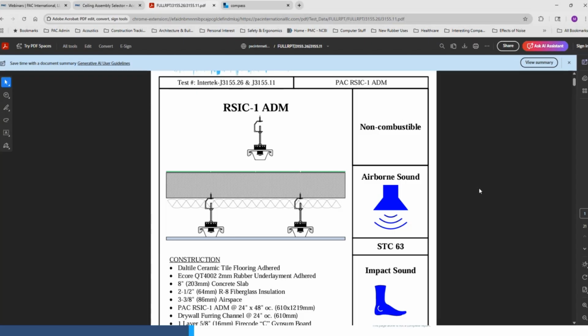So you're trying to measure the sound that's just coming through this opening, right? For a floor ceiling test, and I wish I had a better visual for this, you have basically two big boxes, one stacked on top of the other, right? And you make noise in one and you measure the noise in the other one. Well, I guess you measure it in both and you're trying to figure out the difference between them. And that's how much noise the assembly is reducing in the transmission.